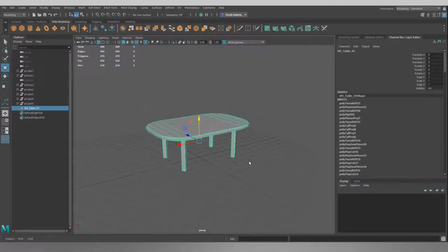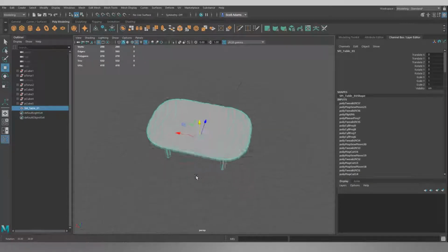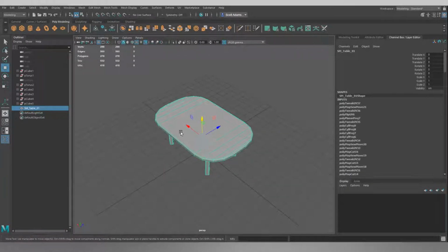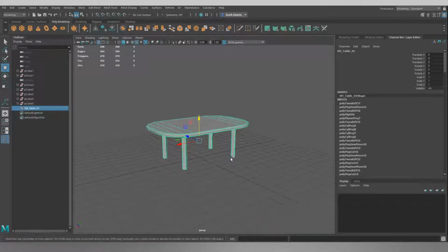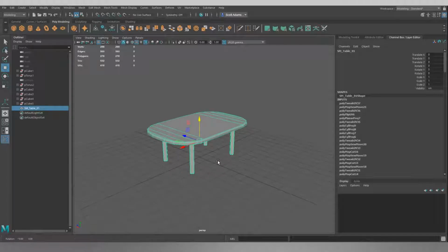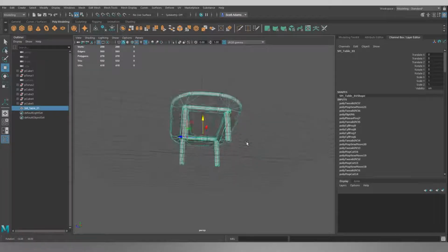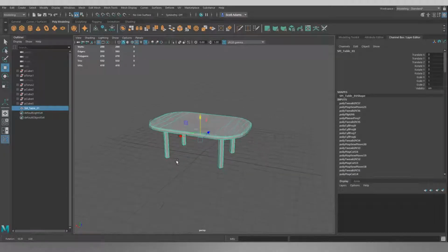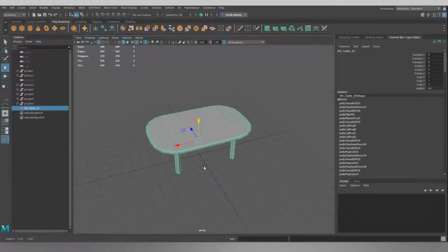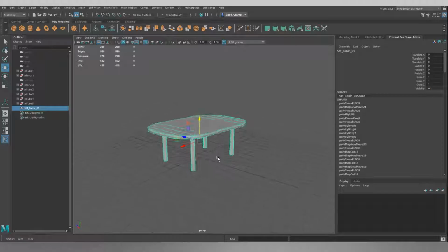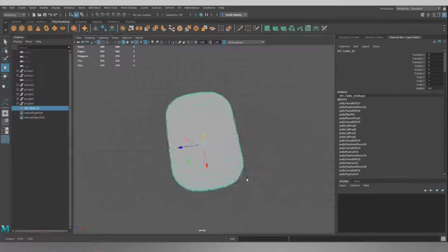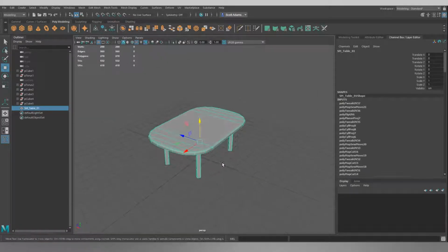The reason we want things facing positively down the X direction is that if all your models face in a consistent direction, when you put them into the game engine, everybody knows exactly which way is the front on the model, how things are meant to sit and look as well. On top of that, it removes the need to apply rotations or any sort of edits to the model in engine just to get things facing the right way around and such, or it lessens the need for that.